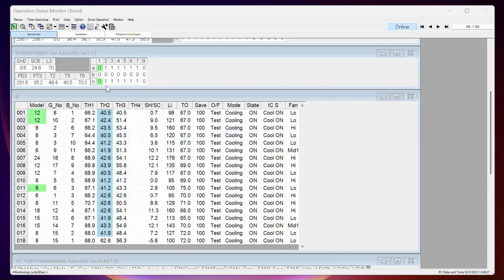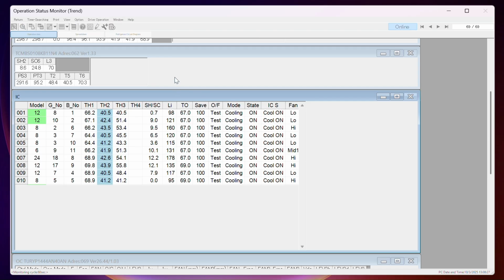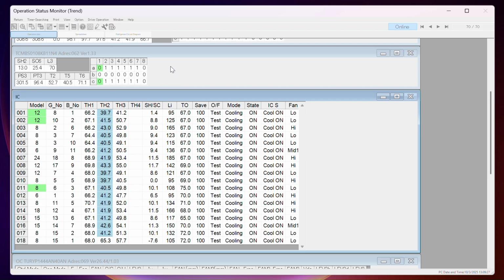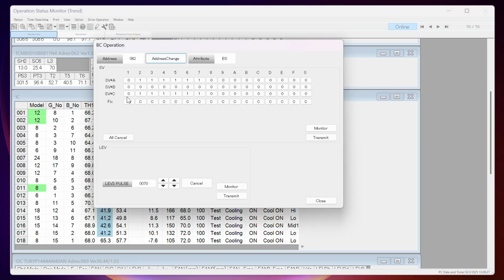We're now looking at, so we were looking at number 1 on the sub BC, and we see that this device lost refrigerant, which is port 1, and I know that it's on the sub BC, or should be, because 62 minus 50 is 12, and 12 and up, this happens to be 18, are there. So let's go ahead and clear our override on the sub BC, because this would just be rinse and repeat to make our way through until we finished all the ports.